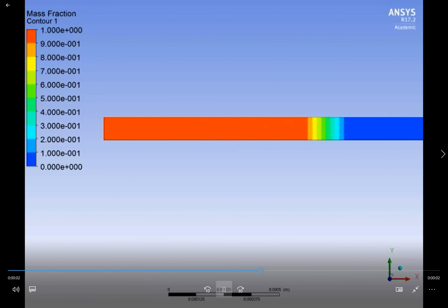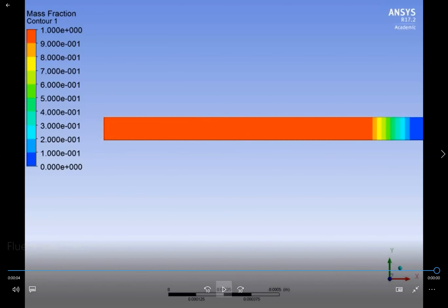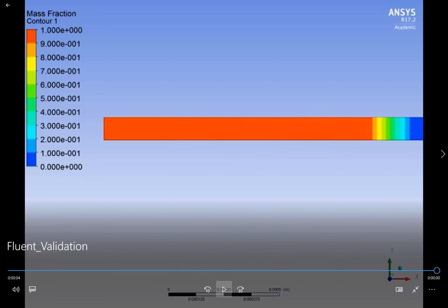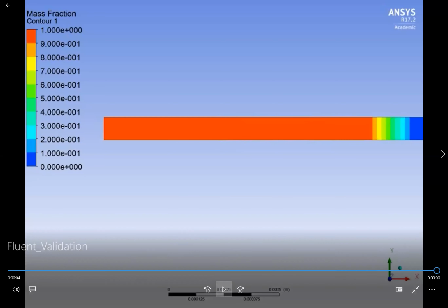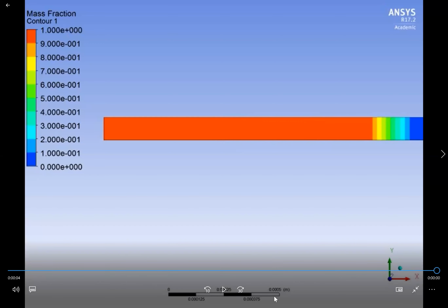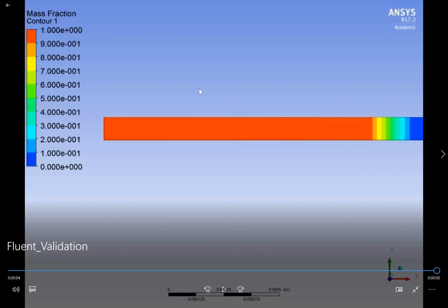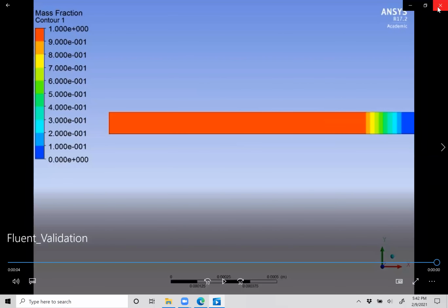The time step was on the order of about a microsecond. And this was a simple 1D domain with like 10,000 cells. And we're talking about a couple days worth of sim time to move. And if we look at the scale bar, 0.0005 meters, so half a millimeter. We moved about 1.5 millimeters after a couple days. So that is an explicit scheme with an incredibly small time step, which is good.